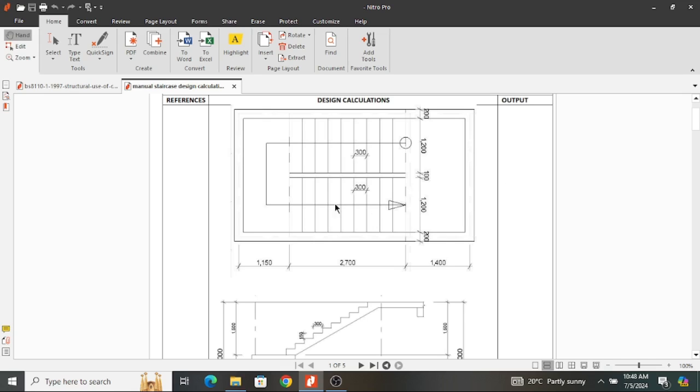There are some staircases where I have this stair and then this flight. I get to my first landing, and then sometimes there could be a shorter flight here of, let's say, 3 or 4 steps. And then I get to another landing, then I proceed to the other flight. Sometimes these steps might confuse somebody, and you might want to design the staircase as having its support from this end.